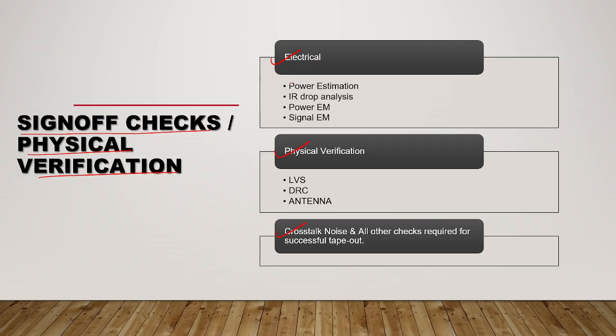In electricals, you are going to check power estimation, IR drop, power EM, and signal EM. In physical verification, you are going to study layout versus schematic, whether your layout is matching your schematic or not. That is LVS.